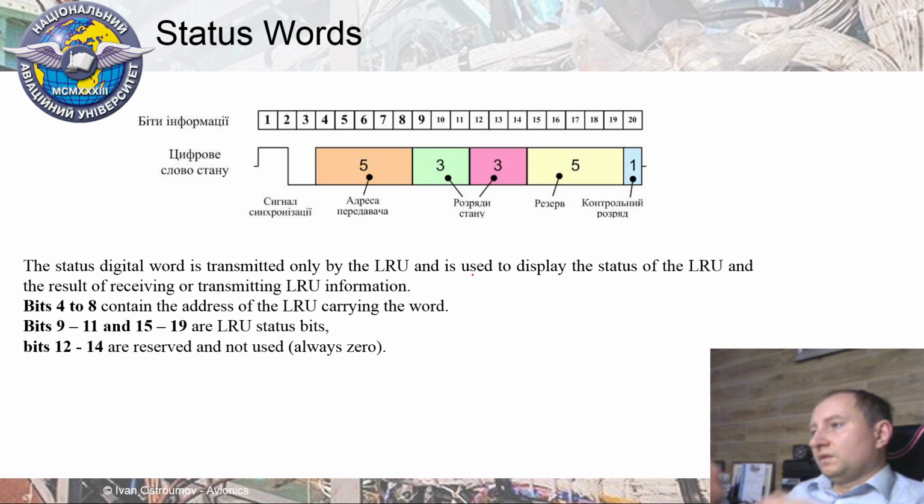And status word. Status words can be issued by LRU to specify a mode of LRU or its status. It means if this LRU is ready for transmitting, or if this LRU received the whole sequence of data and this transmission was successful.